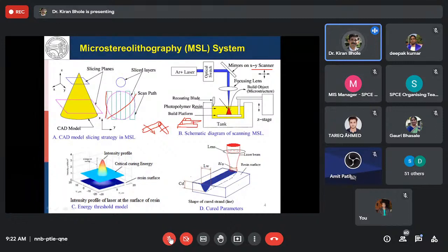It is a very important point, because in actual fabrication, this photopolymer may have a viscosity of the order of honey, or maybe a clay or grease type of resin. Take honey, for example, which is easy to understand: if you dip this platform, are you going to get a 5 micron fine layer on top of this platform?